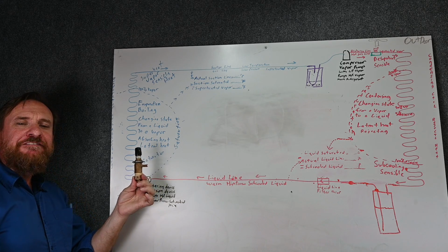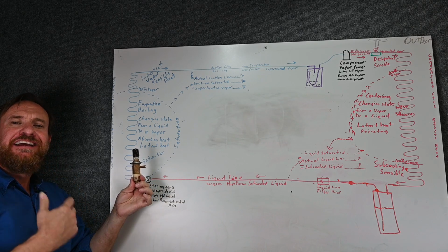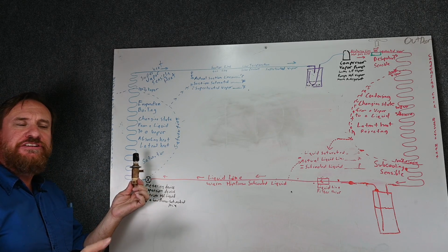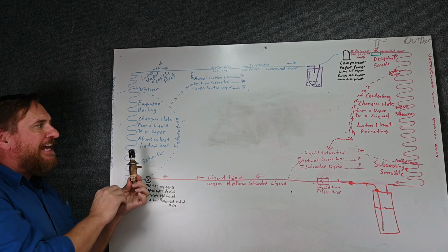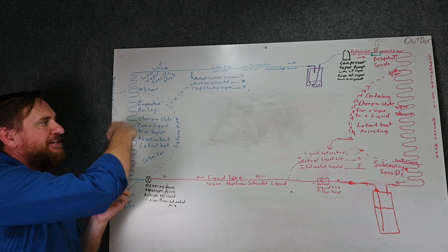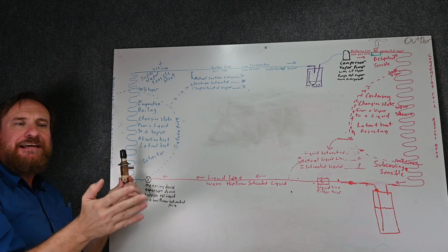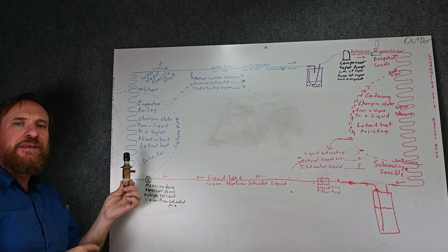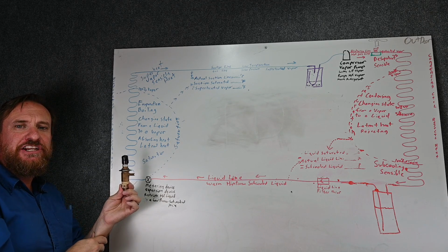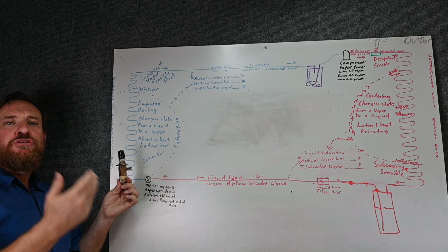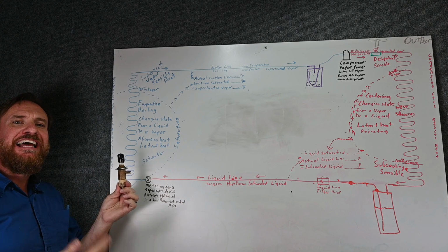Let me explain. If I installed this system on a regular house AC, and the system was near design conditions, and I adjusted this perfectly, it's possible that I could have this much saturation, and most of this would be at 40 degrees in those lab conditions, and everything would be good. But let's talk about when those conditions change. Let's say the system had been off for part of the day, and you're trying to cool the house back down. This is what we call a heavy load.